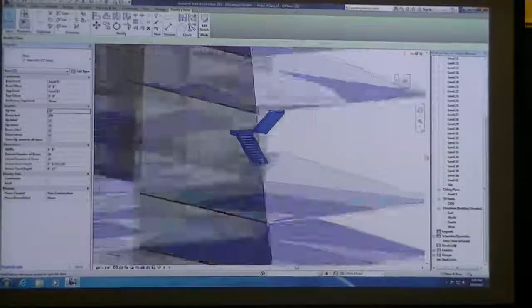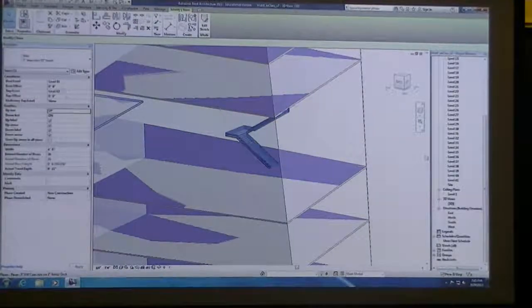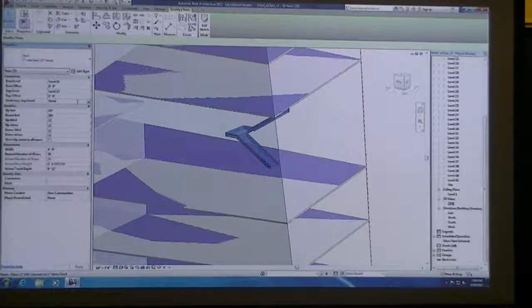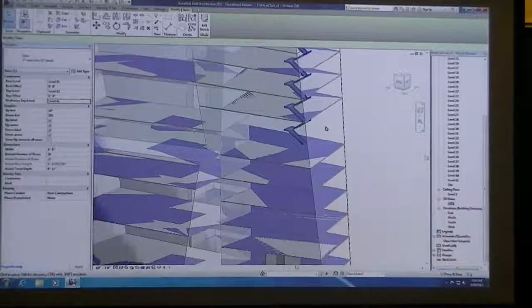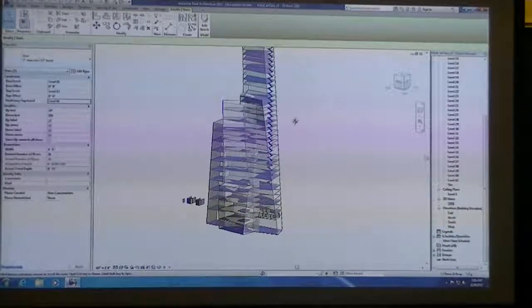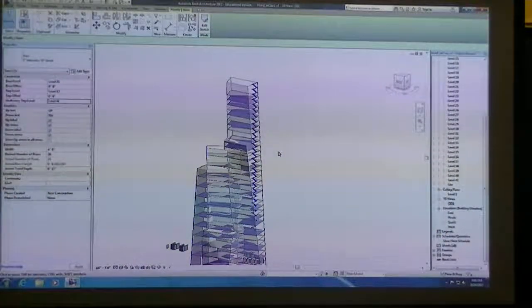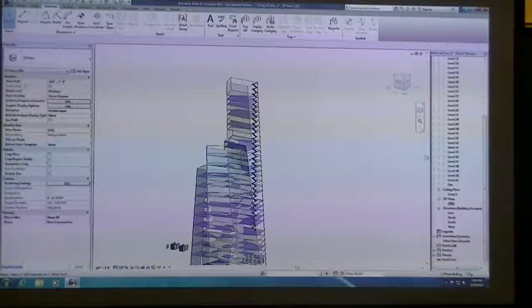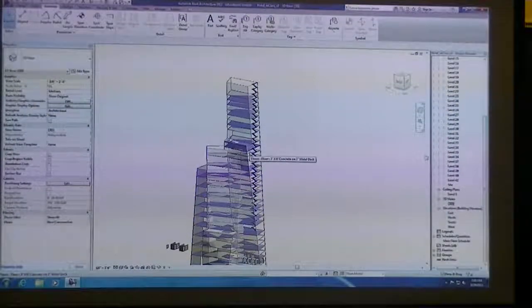But if you select a stair, you can also pick that instead of just going from level 11 to level 12, there's an option called multi-story top level. If you change that from none and go ahead and select something greater than level 12, that stair will copy all the way up to whatever your top constraint was. Then you don't have to model this over and over again. You just do that one time and you're done.